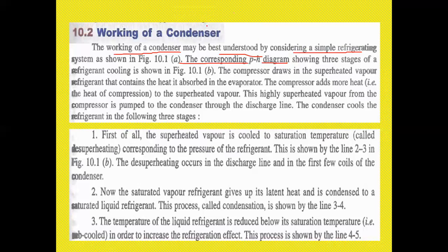Now see here, figure 10.1 shows the corresponding p-h diagram, showing the three stages of refrigerant cooling. Figure 10.1b shows the compressor draws in the superheated vapor, which contains the heat it absorbed in the evaporator. The compressor adds more heat to the superheated vapor.